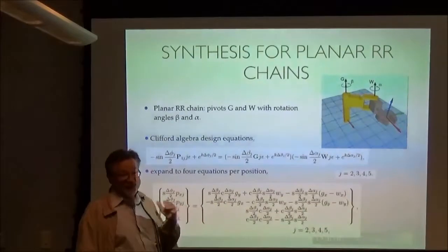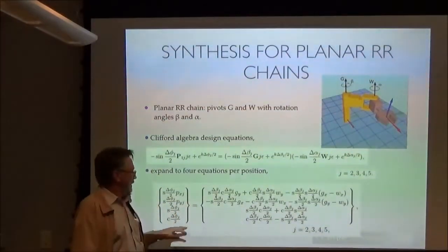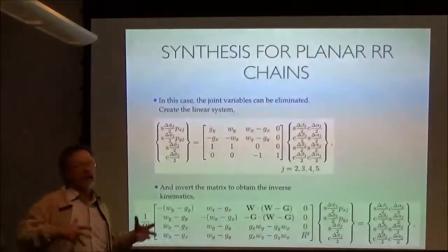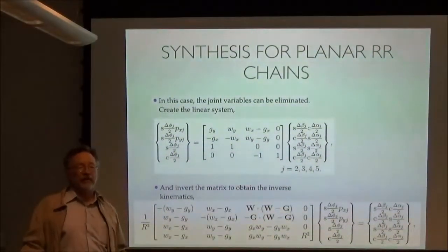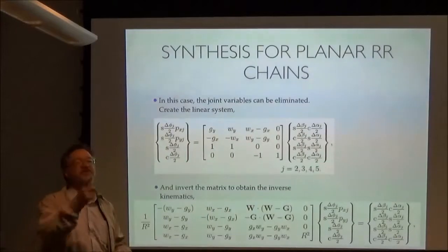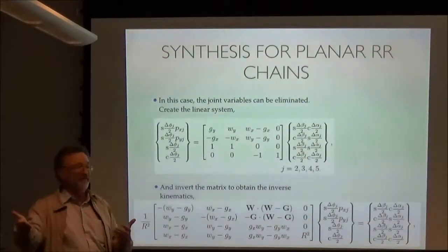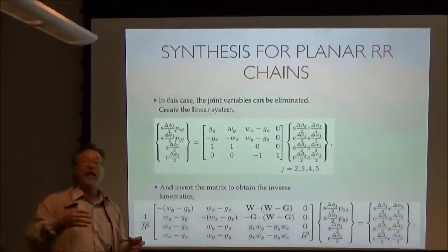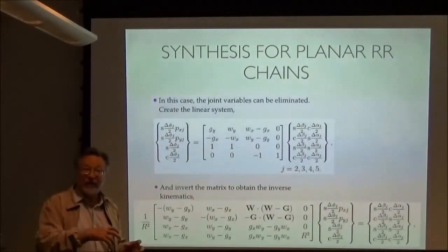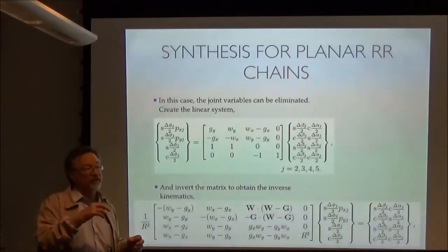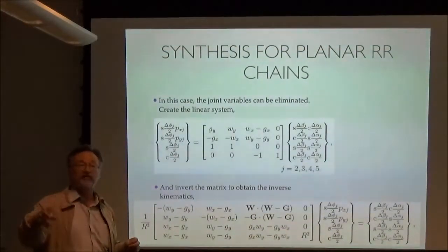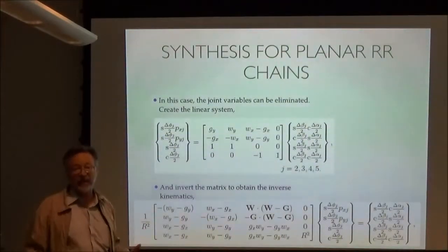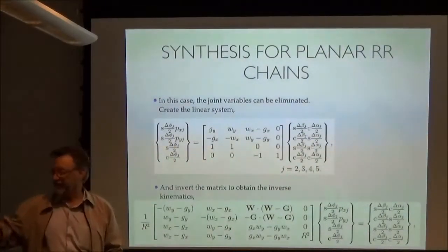And it turns out to be surprisingly simple because what you wind up doing is you wind up getting algebraic equations that we already know. You wind up getting the algebraic equation of a circle. Why? Because that moving pivot has to travel around a circle, around the fixed pivot. Okay. It works. It does, though, help you formulate the problem for not just the 2R chain, but the 3R, 4R chain. And you get a nice set of mathematical equations you can solve for that.